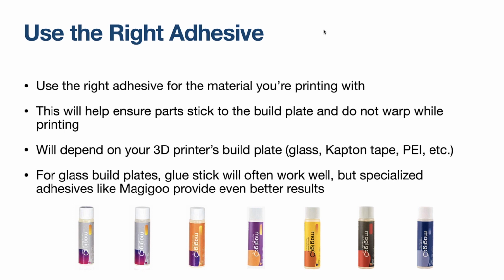A couple things I didn't have time to mention during the live stream. After you get all your slicing done and you're ready to go to the printer, make sure you think about your adhesion that you're using on the build plate. These days there are some really wonderful adhesives available, even for the more advanced materials. So especially if you're printing on just a plain glass build plate, these adhesives make all the difference in the world.